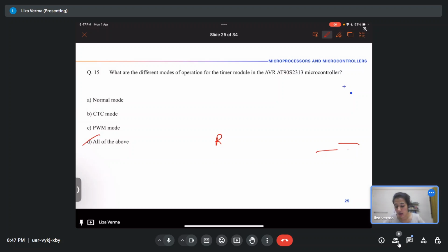And one more thing, normally your arithmetic operations won't affect your flags for the ARM microcontroller, but this is flexible. If you want your arithmetic operations to affect your flags, then you just have to add S to the opcode in the instruction.